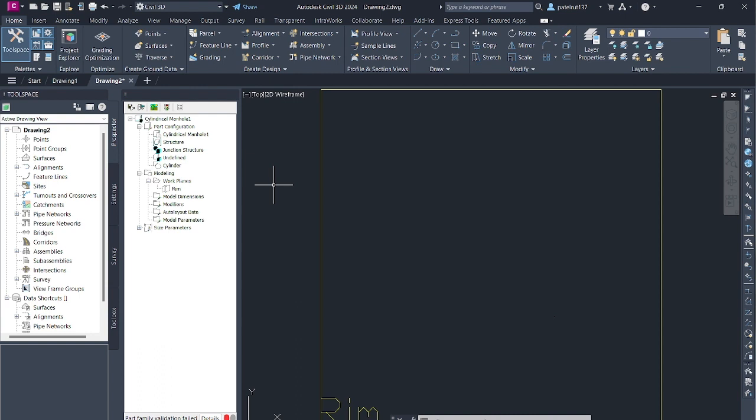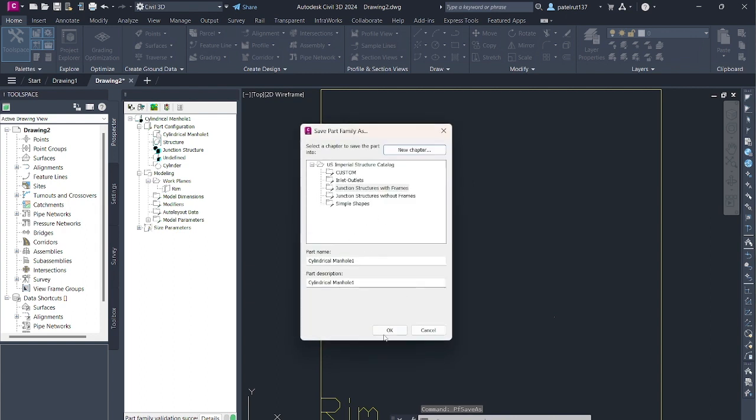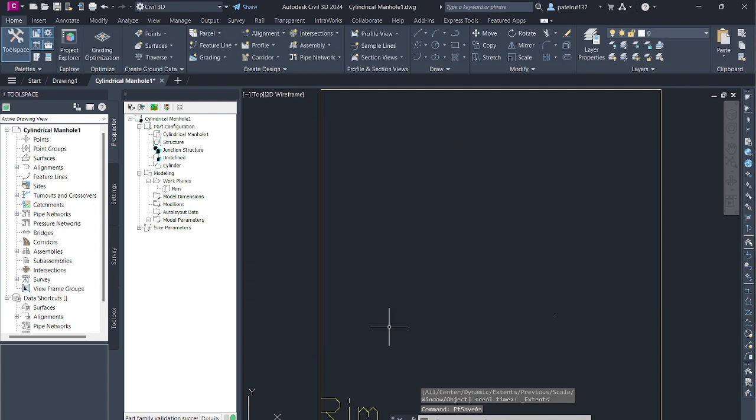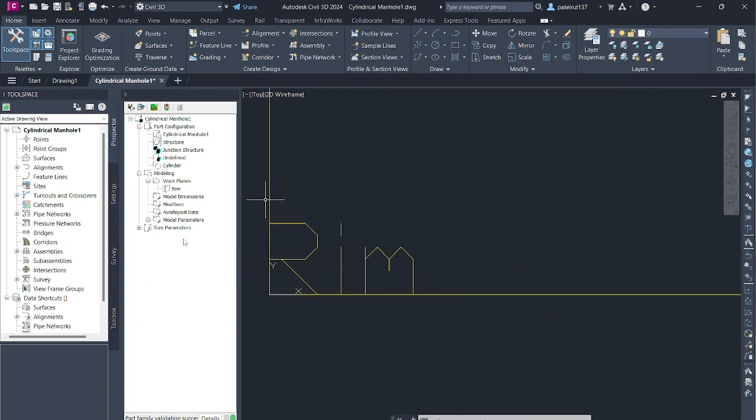Click OK. The next step is to assign some preliminary values to the structure parameters. These will be refined later by adding lists of possible structure sizes. Right-click Model Parameters Edit. The Model Parameters dialog box is displayed. Note that the structure parameters have all been assigned an initial value of 0. Change the numbers in the equation column to match the following constants, all in inches.